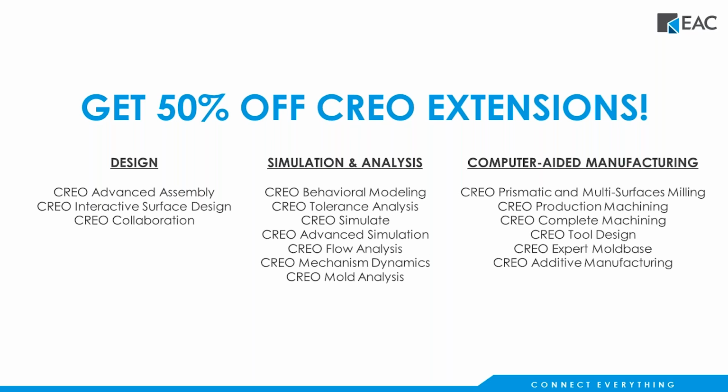As far as Windchill works, Windchill understands multi-body from the standpoint it's just in a PRT file, right? So as far as I know now, it just looks at it as a regular PRT file, not really seeing the individual bodies in there. Again, the drawing for that PRT file would have potentially the bill of material listing out those bodies. But again, I haven't tested that out, but that's what I would suspect until I find out differently. So thanks for your question, Mark.